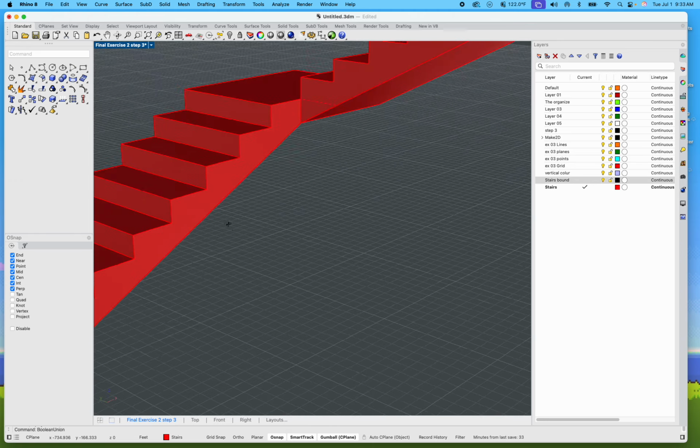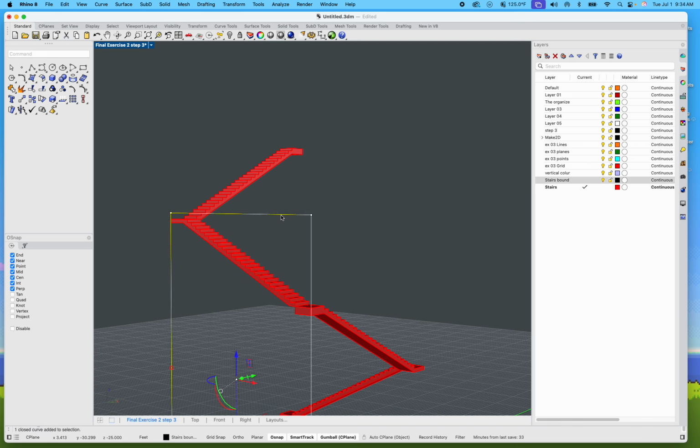I think we overdid it a little bit, so I may need to even wire cut it. Good thing I have that bounding box. I'm going to go straight across. Oh, maybe it doesn't hit. Oh, it's touching it, so it's not going to wire cut if it's touching. It's okay. I can move it out just a little bit, then wire cut it.